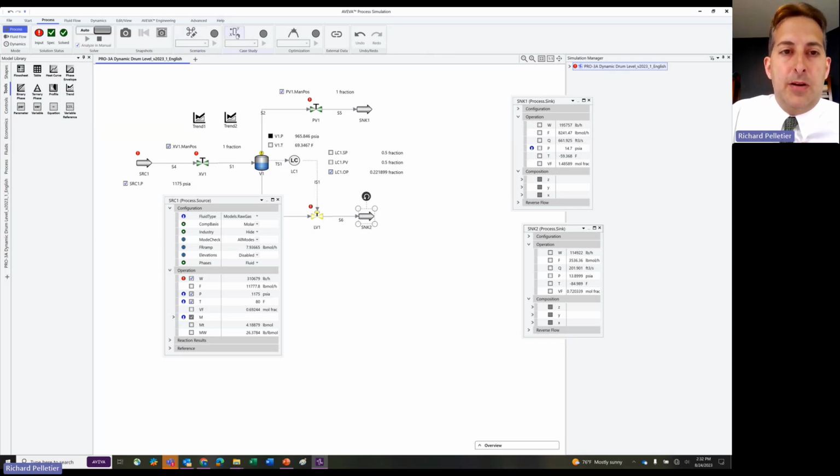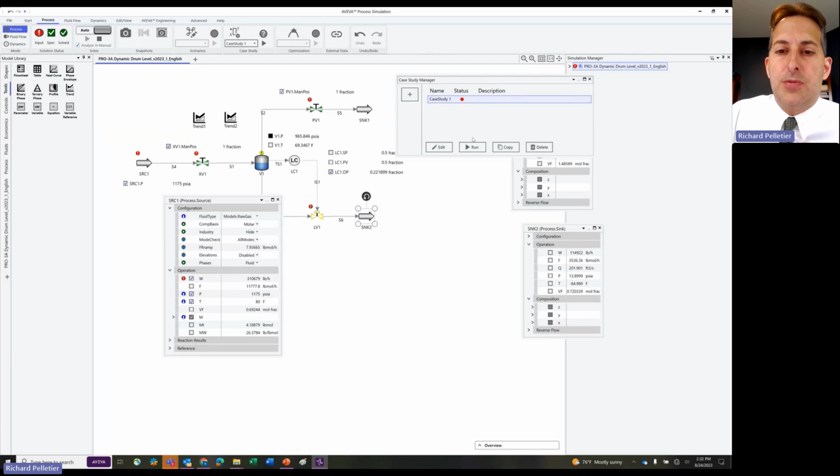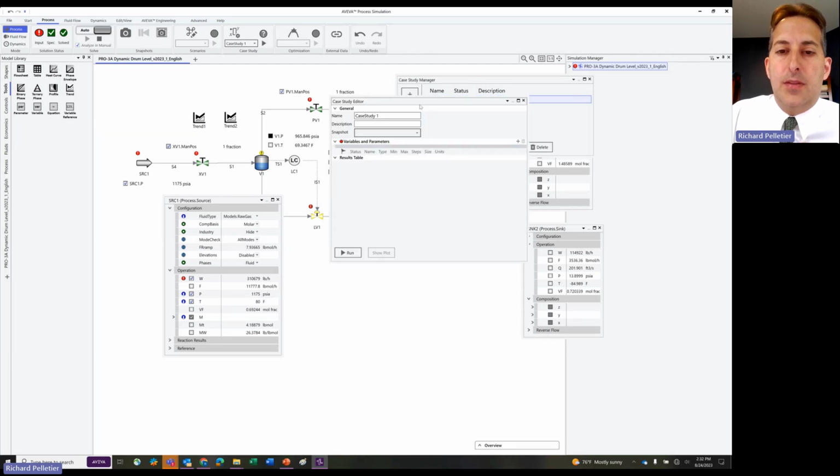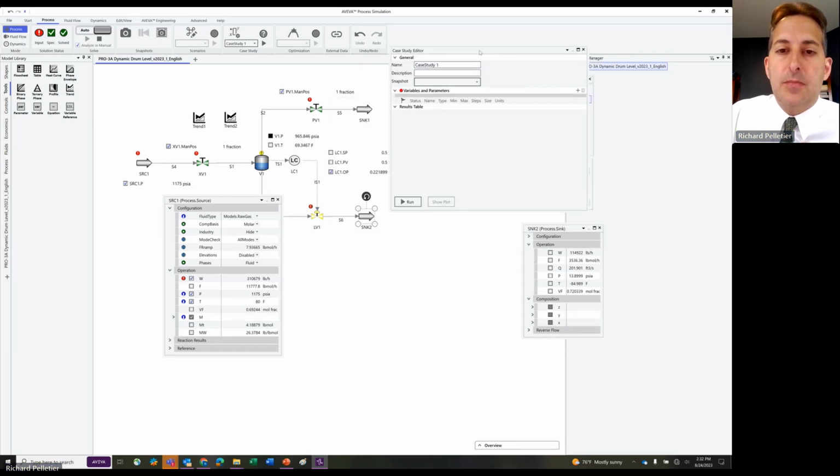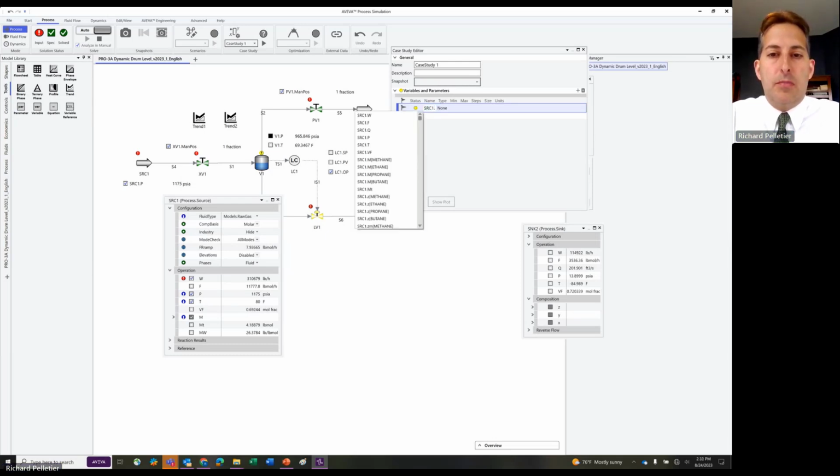All right, so we're going to come up here. We're going to go case study. This is the manager. We're going to add a new case study. We can give it a name and description. Click edit to start setting this up. And we're going to set it up for source 1 mass flow rate because we want to be able to change a property that's specified, right? We can't change a property that's calculated, right?